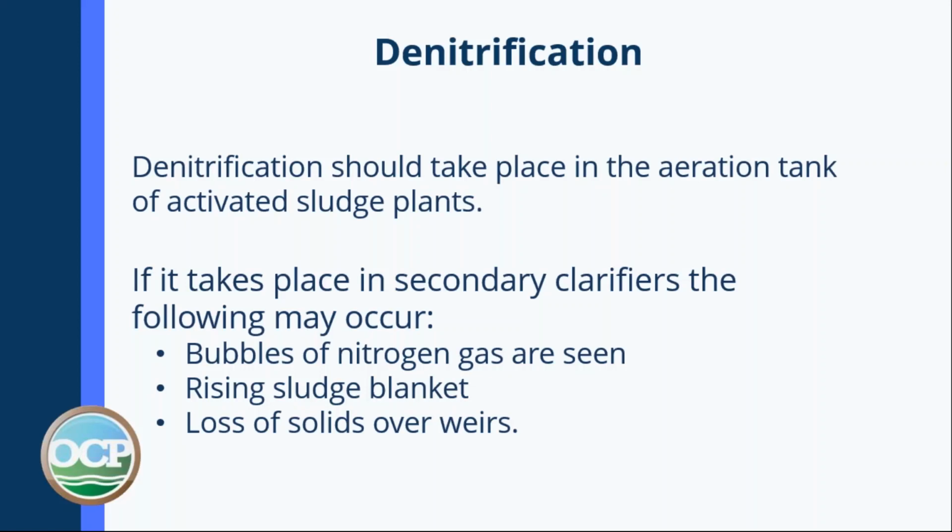If it takes place in the secondary clarifier, the following may occur. You'll see bubbles of nitrogen bubbling to the surface in your clarifier. What these bubbles of nitrogen will do is they will cause the sludge blanket to start rising in the tank and can push solids over the weirs. You could be out of compliance with total solids.